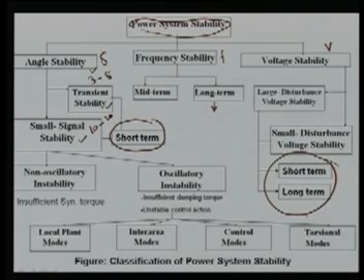The short term voltage stability involves the dynamics of fast acting voltage components such as induction motors, electronically controlled loads, and HVDC converters. The study period of interest is in the order of several seconds, and analysis requires the solution of appropriate system differential equations. This is similar to the analysis of rotor angle stability. Dynamic modeling of load is often essential in this case, and in contrast to angle stability, short circuits near loads are important. It is recommended that the term transient voltage stability not be used. Normally, we should not say it is transient voltage stability. So, always we have to call it short term voltage stability.